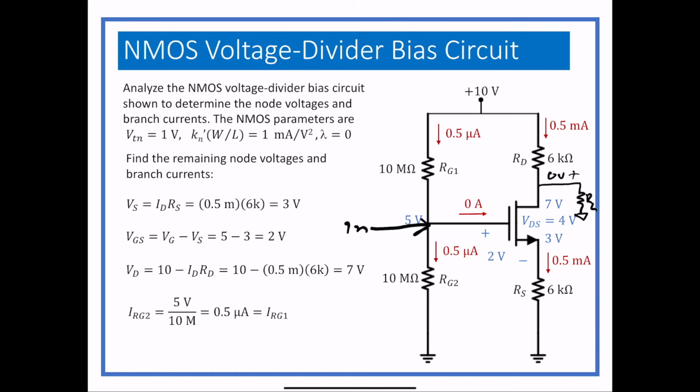And as you'll see next week, there are ways to isolate the in and the out. Usually you put a capacitor between the input and the gate, and you put a capacitor between VDS and output to take the DC away. But you don't necessarily have to, but you should if you're really going to use it. So right where the 0 amps is, that's where you put a cap? You put it like here, and then you would put one here. And that would kind of isolate the output from the input. We'll do more of that next week when we talk about AC circuits.